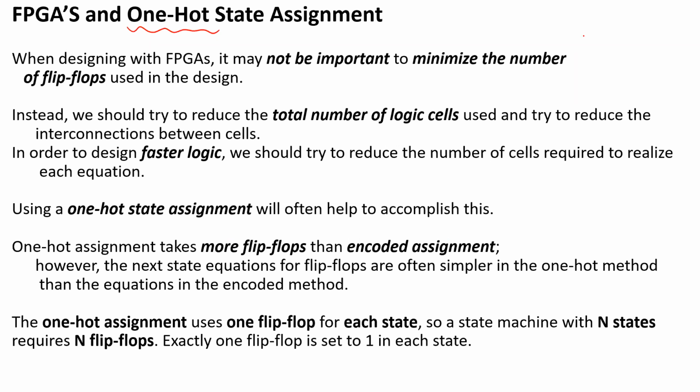For example, we have a state diagram here. S0 is there, S1 is there, S2 is there, S3 is there. How many states are there? Depending upon the input signal, we can generate the state diagram, something like this. If you are considering a design consisting of this many states, how many flip-flops are required? As we have seen, 4 states are there, so two flip-flops are more than sufficient, right? So 2 flip-flops are sufficient.